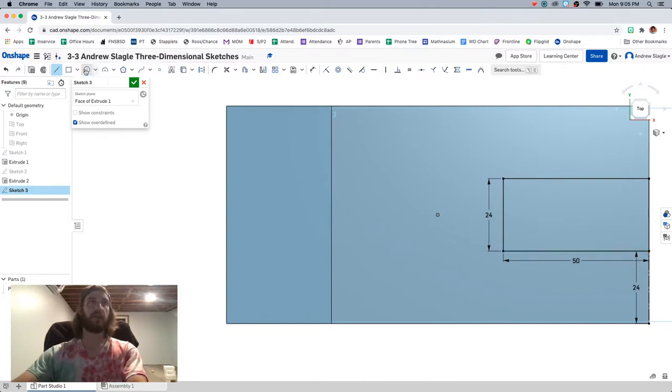And now to create that circle shape on top, we're just going to grab this, well, I guess it's a semicircle. We're going to grab that, and the way the circles draw is they start in the middle and work outward. So what we can do is we can come and find the midpoint of our line, sketch out, click to there, and then we've got this nice perfect shape that we're looking for.